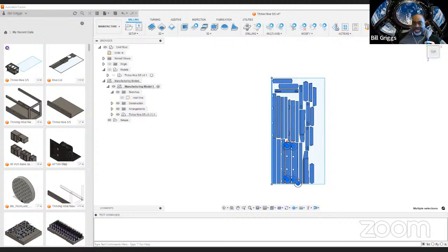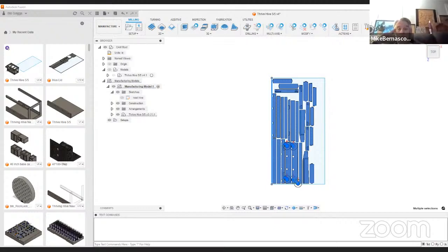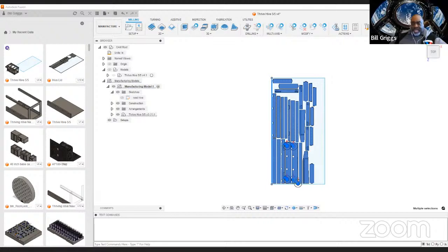And in Aspire, here are those parts laid out. You see these orange parts, they don't look like they line up, but they actually do, because I want them to cut oversized so that the entire pocket is cut. All right. So there's a little manual file work done, but once I get to that point, I can group these parts. Let's say this part, this part.